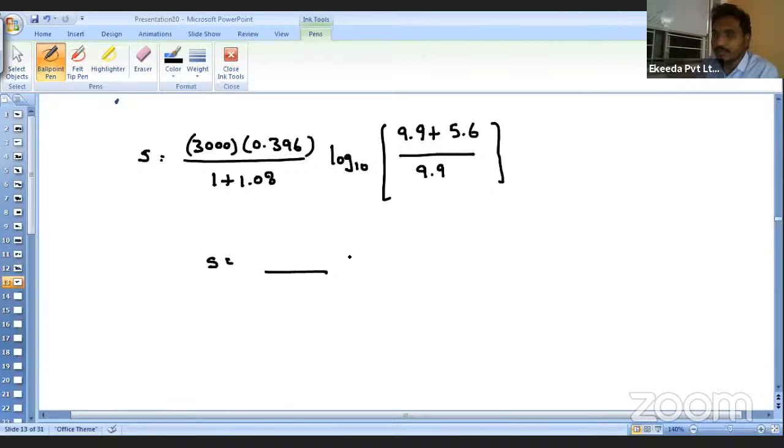So here the point is, in the present problem, if we know the liquid limit equation, then we can find out the compression index, and the initial thickness is given and the initial void ratio is given. Because of the natural deposit of the soil and the construction of the foundation, we should know how to calculate the effective stress at the center of the clay layer. Then only we can obtain the settlement value.